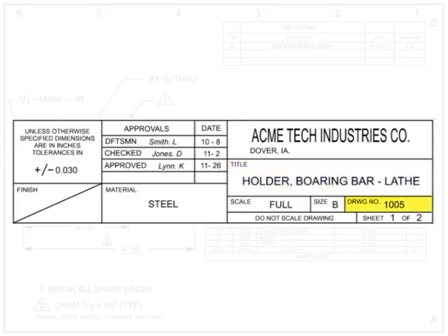The drawing number gives the drawing a unique identifier as a standalone document. Older drawings sometimes use the part number as the drawing number. This is considered bad practice in modern drawing standards. In modern standards, document numbers, such as drawing numbers, should remain separate from part identifying numbers to simplify and separate both the document change and part change processes. However, drawing numbers can be incorporated into part number sequences by simply adding an extra digit to the end of the drawing number.